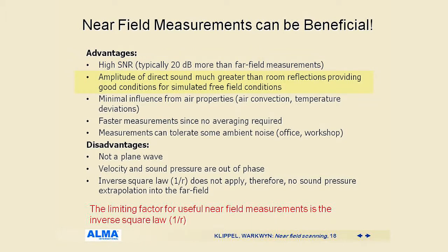Amplitude of direct sound much greater than room reflections, giving good simulated free field conditions. Minimal influence from air properties, air convection, temperature deviations. Faster measurements since no averaging is required. Measurements can tolerate some ambient noise from the office or the workshop.